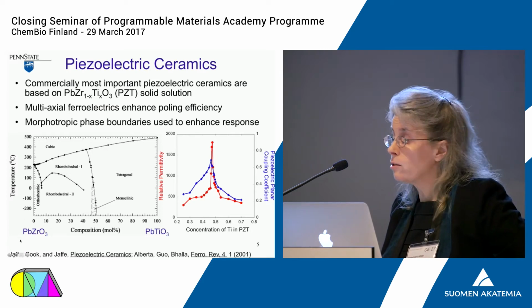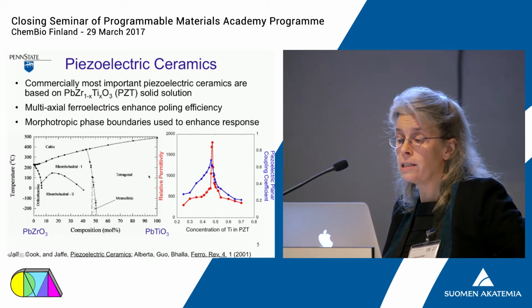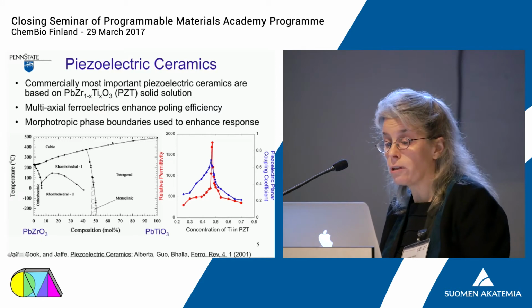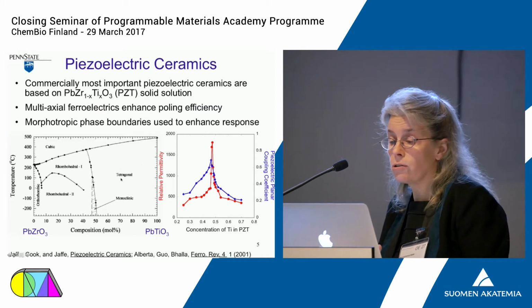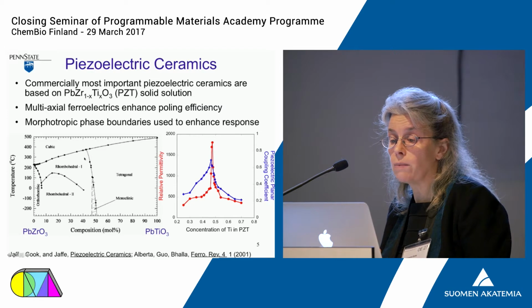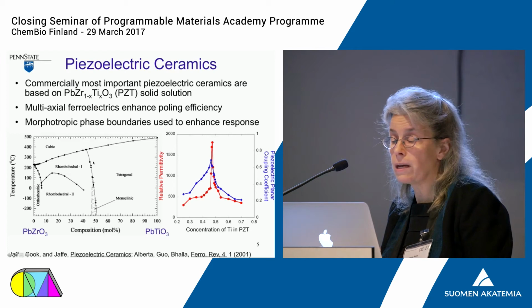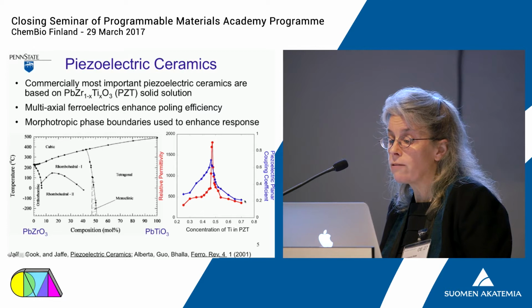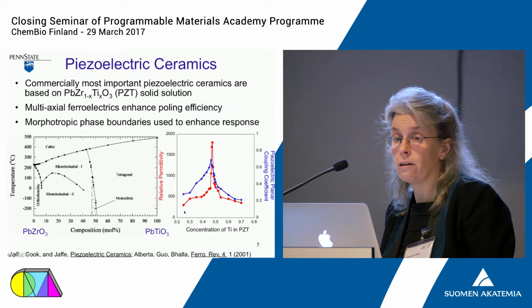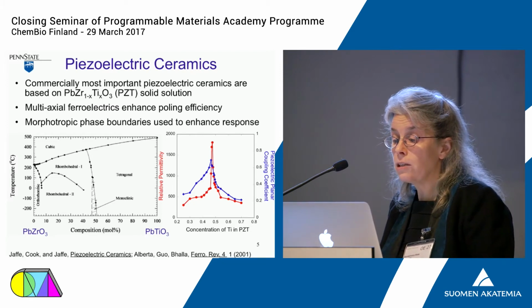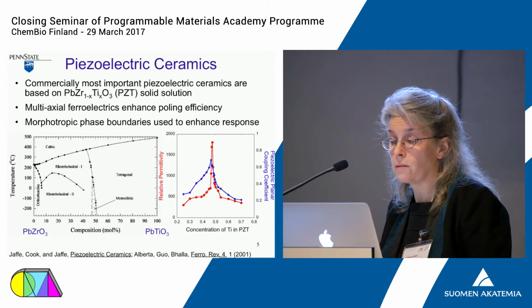Here is the phase diagram for lead zirconate and lead titanate. Below this line, which denotes the Curie temperatures of the solid, the material has a ferroelectric distortion. On this side, the material is tetragonally distorted. Over here, it's rhombohedrally distorted. And we have a nearly temperature-independent phase boundary between those two. At that temperature-independent phase boundary, we have a significant maxima in all of the coefficients that depend on polarizability, including the piezoelectric responses.